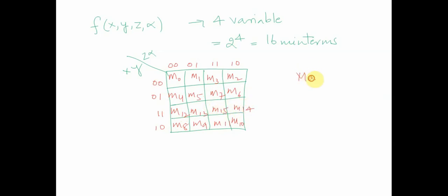The mapping of truth table to K-map remains similar, just that we have a bigger block. That's why in the beginning, when I spoke about K-maps, I said this visualization gets harder as we move on. With 4 variables we have 16 minterms, with 5 variables 32 minterms, and when we move to 6, we will have 64 minterms. The 5 variable one would be like two K-maps superimposed on top of each other, and the 6 variable one would be like four of these superimposed on top of each other, right? Basically analyzing that becomes pretty difficult.